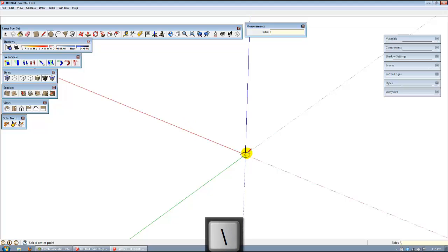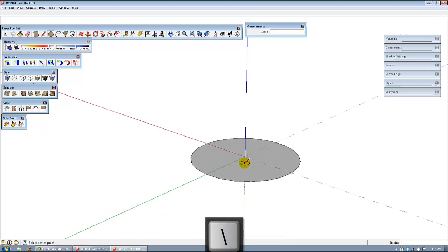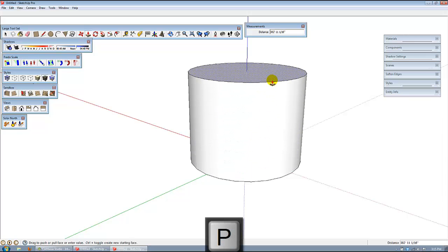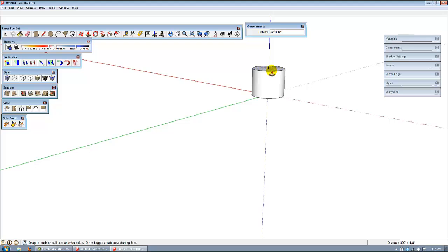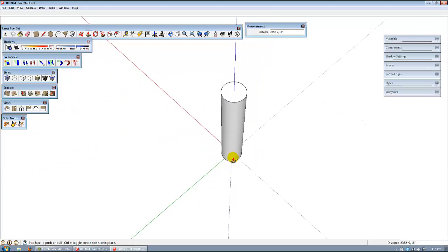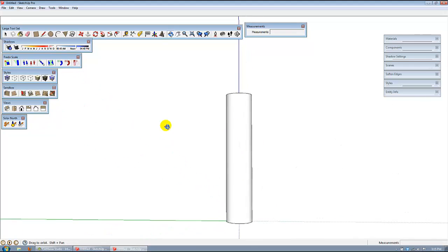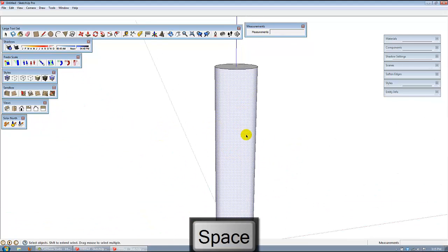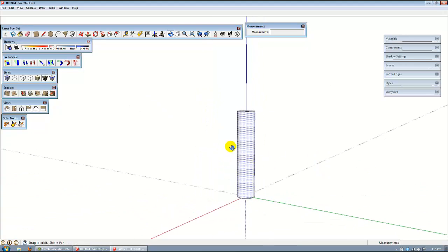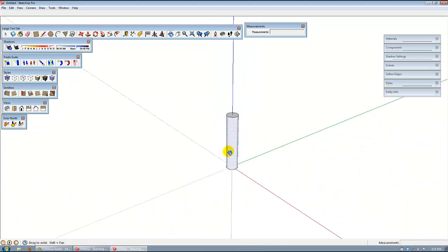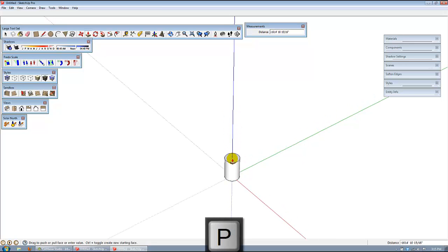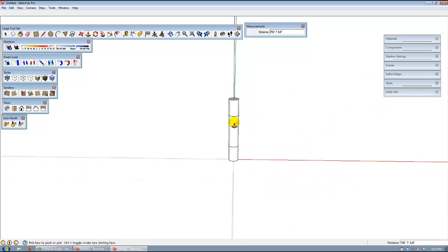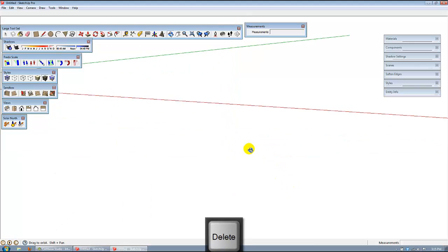Now, just so you know, as a good SketchUp pointer, any geometry with 24-sided circles or arcs is going to slow down your model the more you have it and the more complex your models get. If you pull a circle up like this, you get this nice cylinder, and this cylinder here can be kind of a RAM hog on your computer as your geometry and models become more complex.